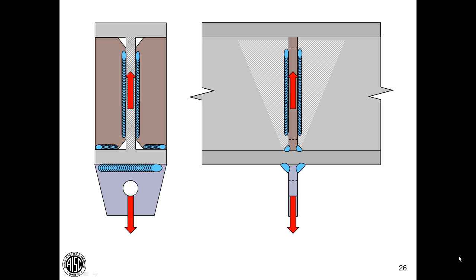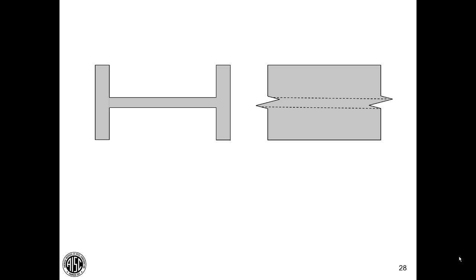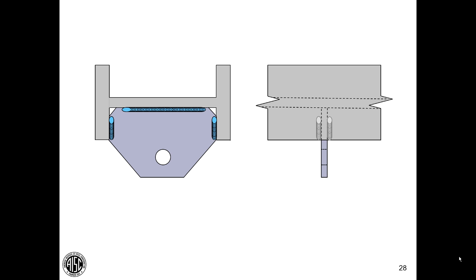As a matter of fact, we could cut that back and create a gap. The load along the length of the weld is still uniform because our load path into the member that lies parallel is still present. Let's rotate that beam 90 degrees. Now we have the web horizontal and the flanges vertical. Let's add in a lug that we want to use to transfer a vertical load. We weld that in place. There's the load. The load wants to go into the member that lies parallel. The force goes to the stiff part. In other words, this vertical load is trying to go into the flanges.